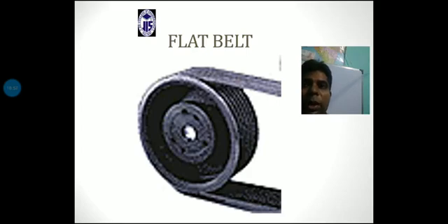Creep of the belt is actually an inverted phenomenon in belt drives. Creep gives rise to a relative motion of the belt over the surface of the driving pulley, and that is based on the tight side tension and slack side tension. Obviously the two side tensions can be calculated, and as the tension of the belt is reduced, the belt shrinks in length.